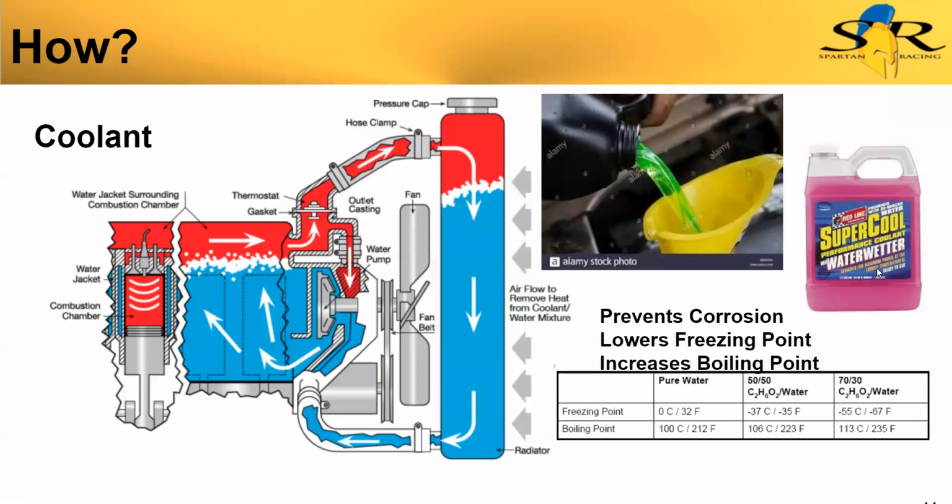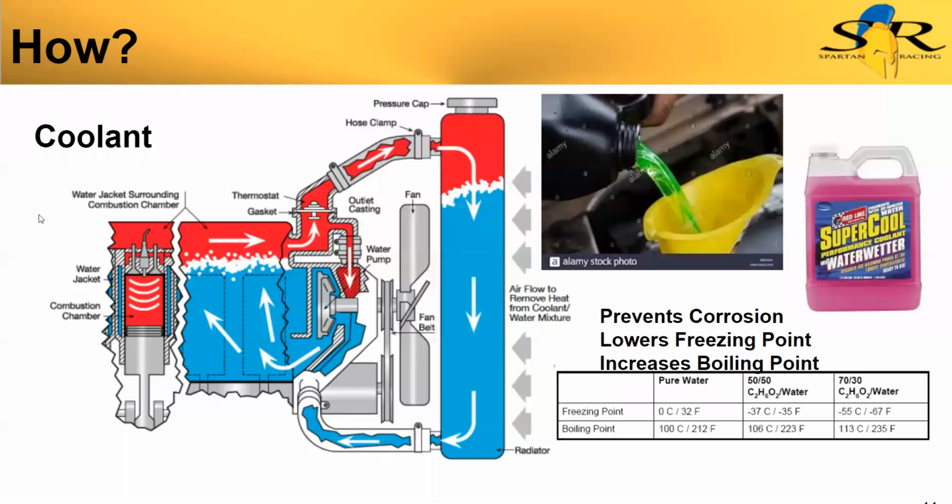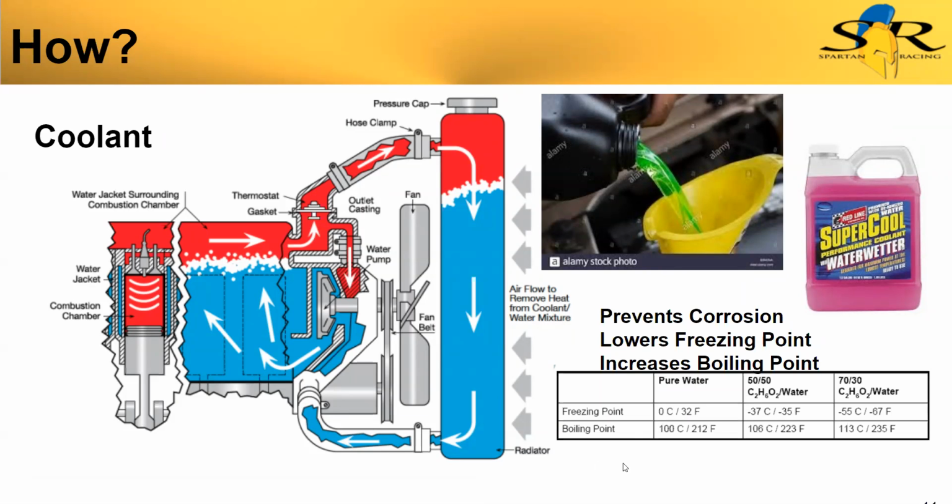There are some performance coolants that also increase the conductivity of the coolant, because propylene glycol, while it does increase the boiling point and lower the freezing point, doesn't conduct heat as well as water does. So there are some performance coolants that are designed to help keep that heat conduction high.